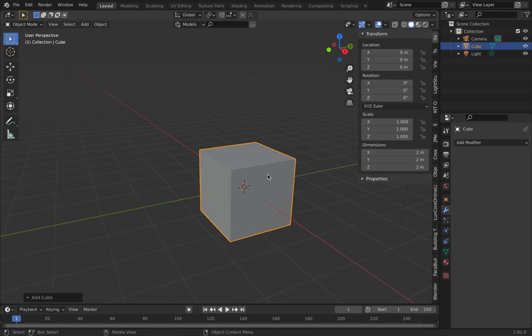Let's not delete the cube, and instead we'll use this to make the cone. There's a reason why I'm not using a cone to model a cone. When you add a cone, oftentimes the sharp edges do not go away even after smooth shading. This is because the edges are either too close or the angle between the edges are far too extreme. The fix for this issue is to model the cone from a cube with a subsurf modifier. There could be a lot of other ways to do the same, but I'm going to stick to this method since this one has worked well so far.